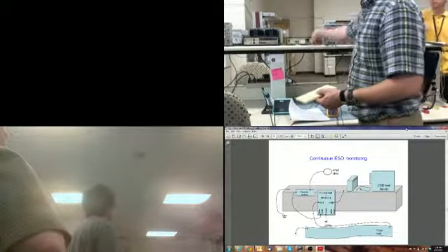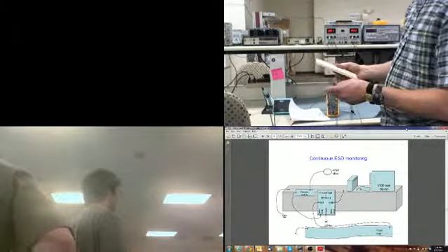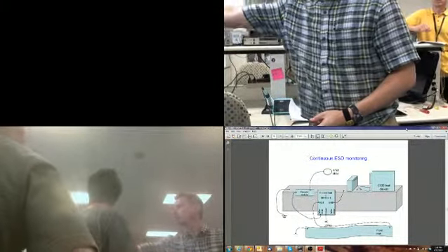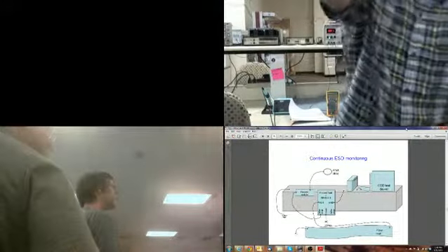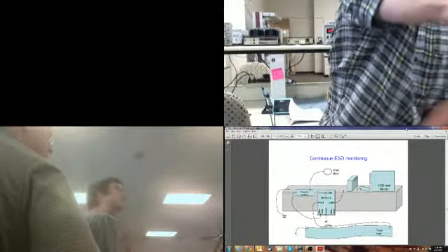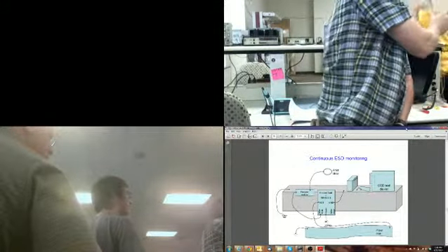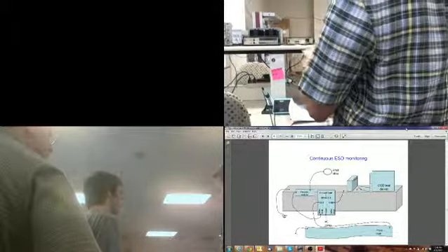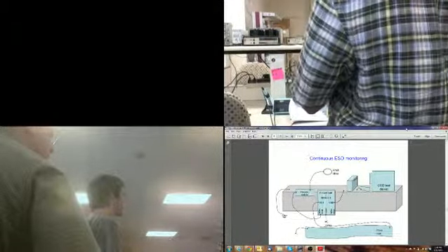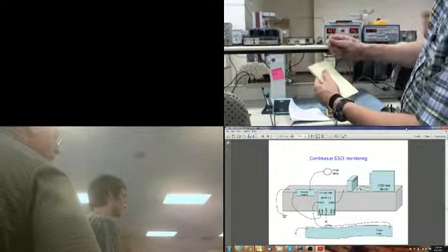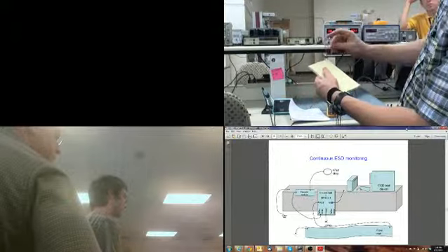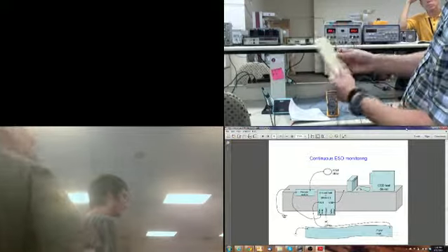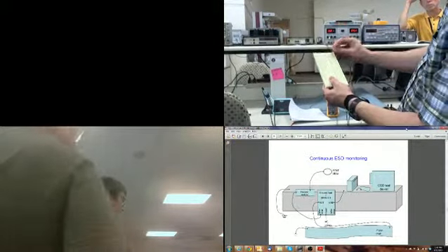For example, let's show you how to do this. If you look on the back of this, you'll see those metal bars on the back of it. Note the direction that the metal bars are facing. Those metal bars mean that these connections will be made when you put something in there. So if I connect this red wire and this yellow wire in that same horizontal bar, and I look on the back of it, see that's the connection. But it will not be connected if I move it down.